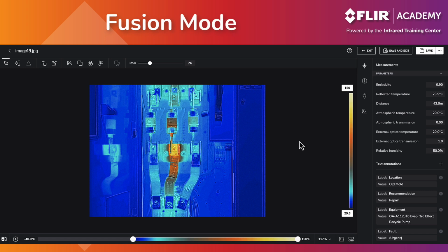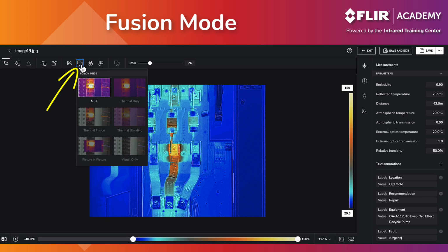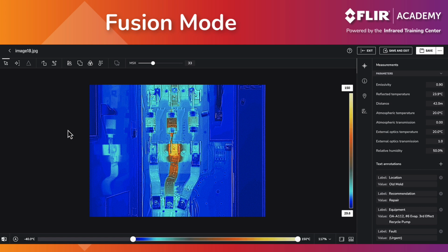Fusion mode offers a number of different overlays that allow you to customize how the thermal image is displayed. This includes Thermal MSX, which adds visible light details to the infrared image. MSX stands for Multispectral Dynamic Imaging and improves contrast by superimposing visible light elements captured by the digital camera on your thermal imager. This includes information such as equipment labels, breaker numbers, or patterns on objects.